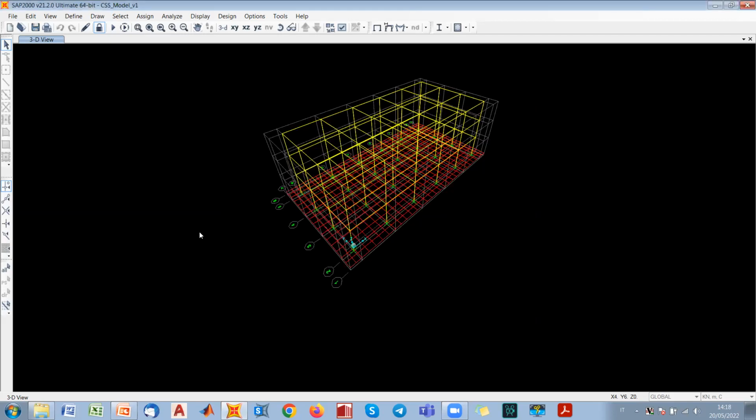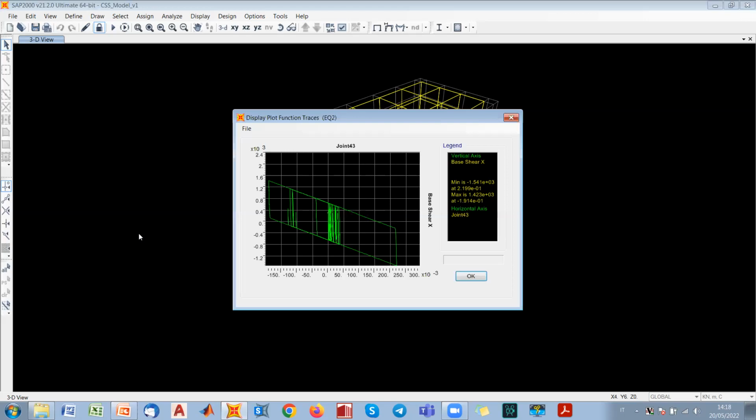For earthquake 2, you see here the maximum displacement is 154 millimeters. Okay, so no, maybe, sorry, this is the force. This is 200. Yeah, the maximum displacement is 220 millimeters approximately. So we are getting closer to the design value, which for curved surface sliders was 180 millimeters.